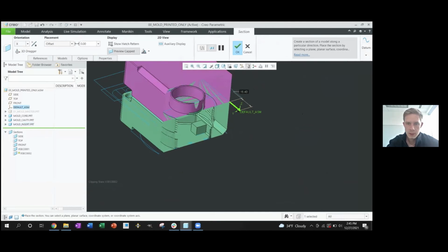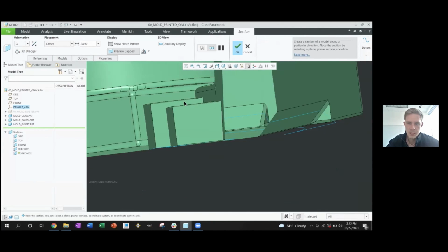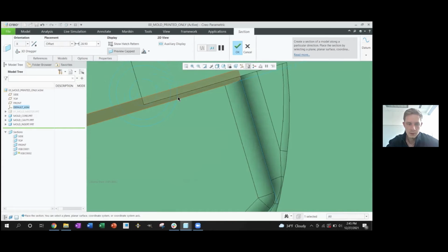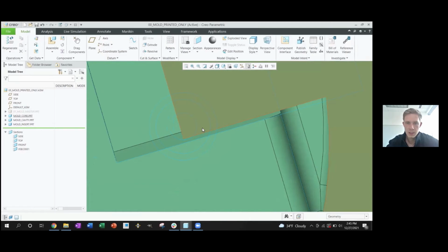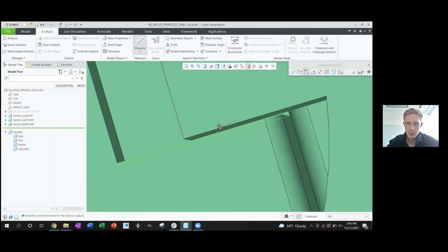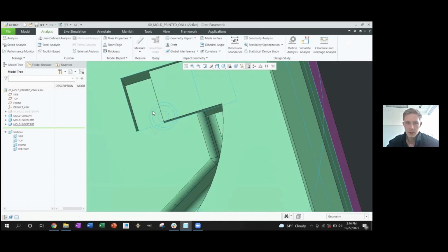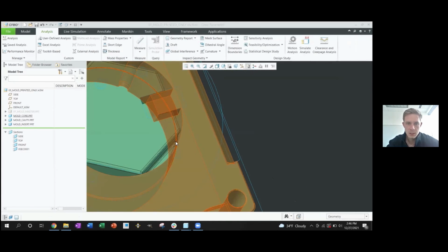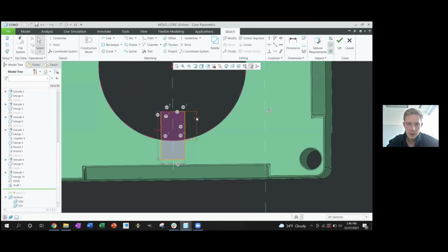Let's take a quick section view here. We can see we have our millimeter of clearance in the height, and we should have 1/4 millimeter of clearance on the sides. We'll just double check that real quick. And yeah, we can see we have our 1/4 millimeter. So let's go ahead and update this. We actually don't have that line for reference here, so we'll just go with 11mm, get it a little bit closer. But again, we don't need to constrain on this end face.